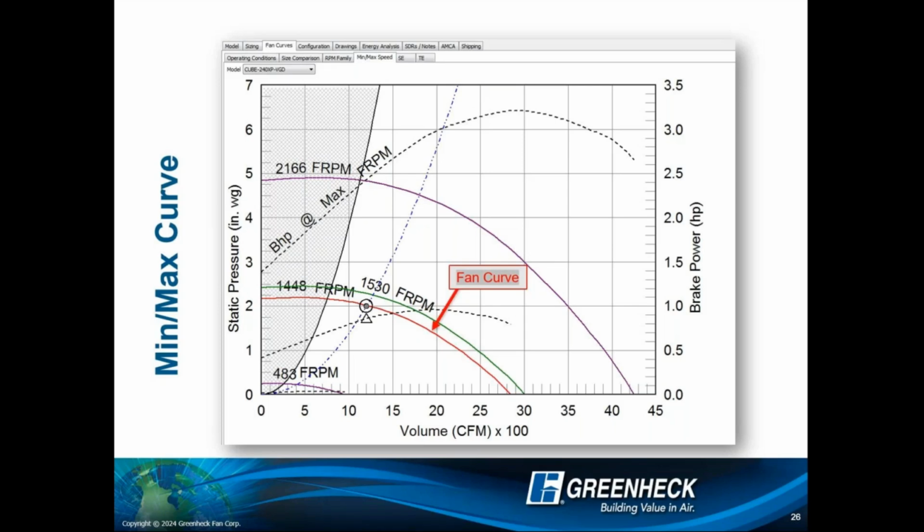What this means is when you did your test adjust balance, right, and you ordered it for 2 inches like we did on the screen, but you actually measured 2.25 inches, you can use that point that you are operating at, knowing it's at 2.25 inches, and you can project, well, if I speed it up this much, what will my new RPM be? You can project that, but only as long as you have not changed your system, right?